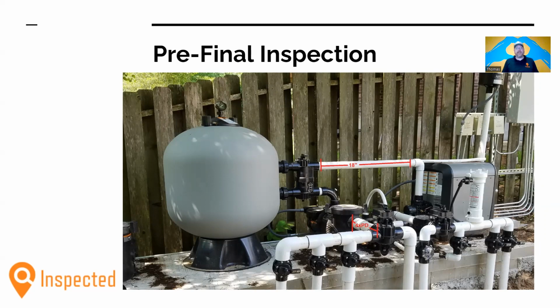Next, there needs to be 18 inches of pipe available after the filter so that somebody who comes in after you, like a solar heating operation, can come in there and tap into your equipment set without disturbing any check valves, required space around a chlorinator, or removing any check valves or any valves that you may deem important for the function of your pool.